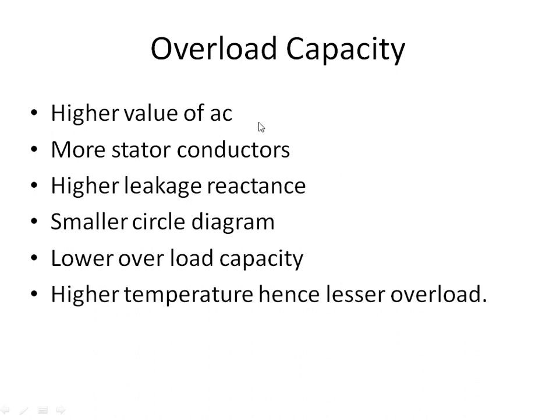The overload capacity. Higher value of ampere conductors will mean that more stator conductors are going to be employed in the motor. This will lead to higher leakage reactances in the motor, and this higher leakage reactance will definitely lead to a circle diagram of the motor which is having a smaller diameter, hence the circle diagram will be smaller, which means that lower overload capacity will be obtained.